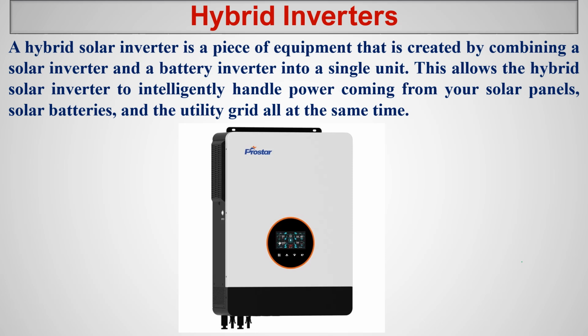So what we can do in off-peak hours is buy the power from the grid and store it in the battery, and we can use it in the peak hours in our house. So it's an energy management tactic, a strategy: during the lowest cost hours, whenever the cost is low, I'm going to buy the power from the grid and store it in the battery.